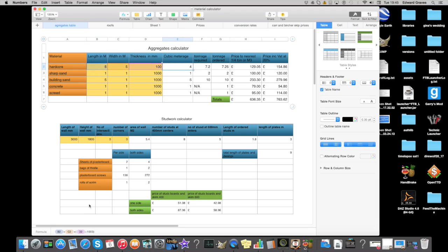That tells me, very basically, and you see down here in the formula, B2 times C2, that times that gives me a square meterage. Fair enough. And then I want to times all of that by D2, which is this in millimetres, divided by 1,000, so I get it into metres. So that in brackets equals the cubic meterage. Done.